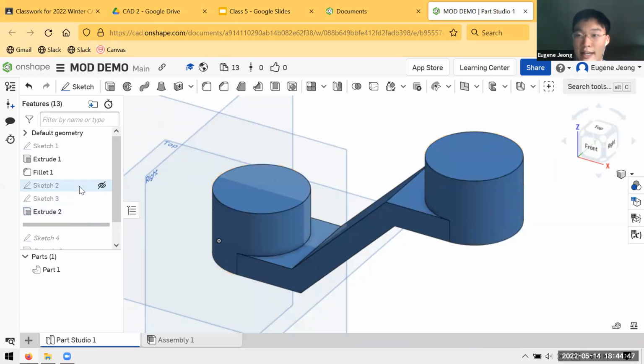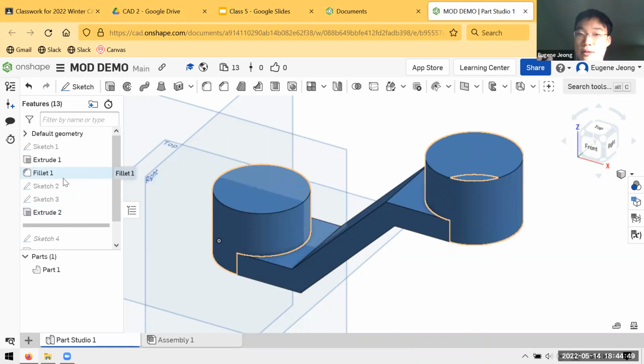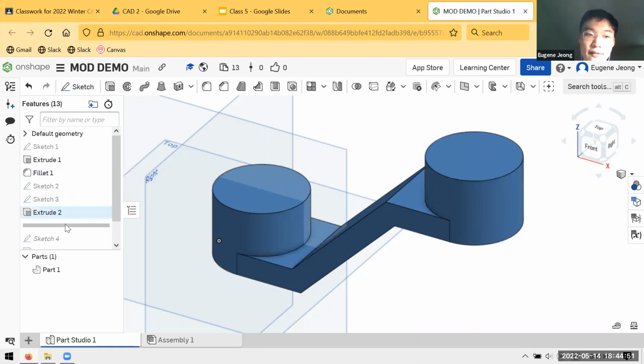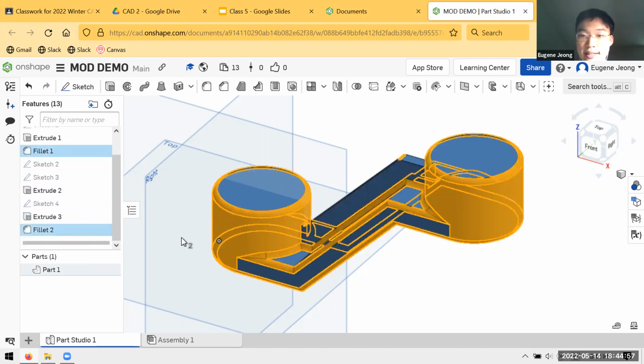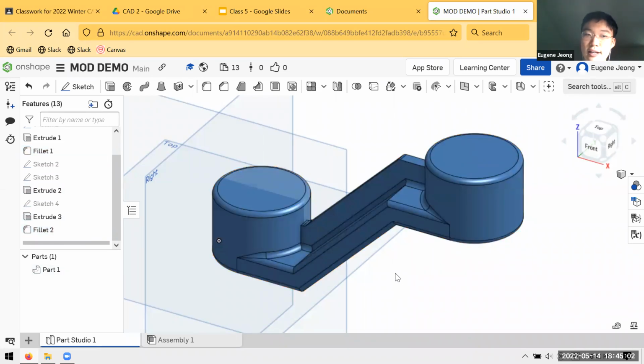It also comes at a higher level when you're working with your whole part. If I'm going to do, for example, fillets, it's often a good idea to put all of your fillets at the end of the document, because if you do a fillet really early, there's a chance that it might end up getting merged into or interfere with another feature that comes later on.